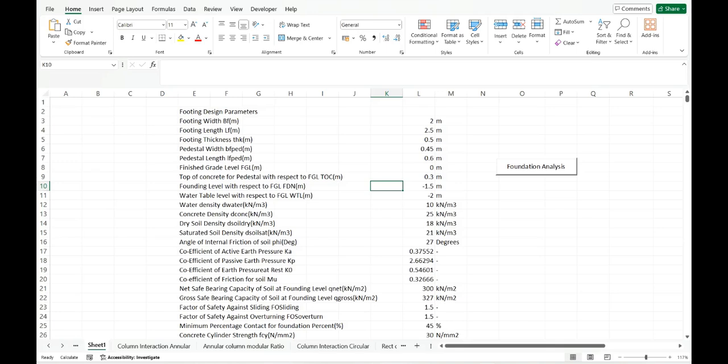as 1, as most of the time columns are tension control, meaning the actual load on column is less than 0.1 fcy multiplied by area of cross section. If the section is compression control, actual load greater than 0.1 fcy into area of cross section, in that case reciprocal load method is used. This is demonstrated in the calculation as the calculations progress. Let us carry out the calculation using the program.